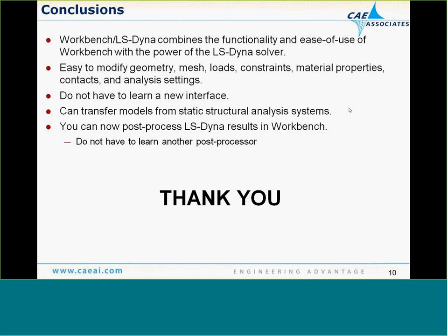One of the other big advantages is that if you already have a model set up as a static structural analysis, you can simply copy that system over to a Workbench LS-Dyna system, and you don't have to create a new mesh. You do have to assign new loads because the application methods are different. The contacts are different as well, and the analysis settings are different.